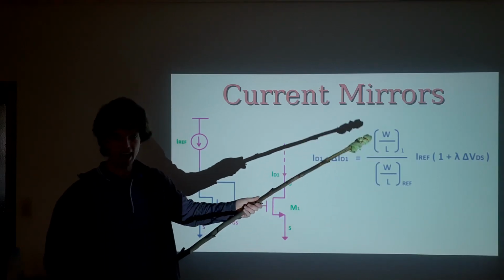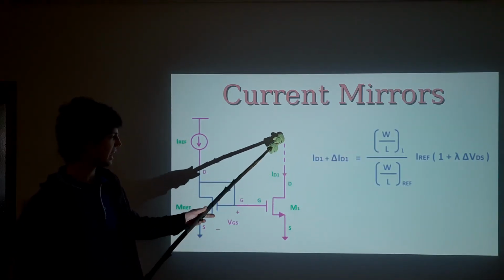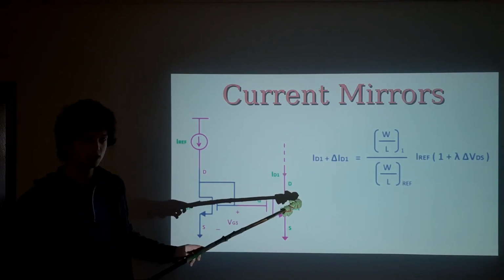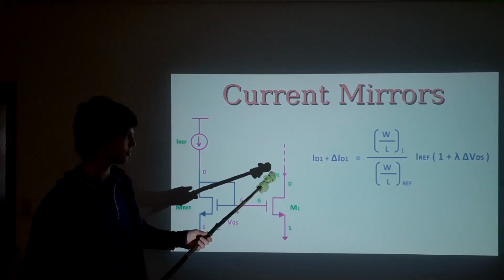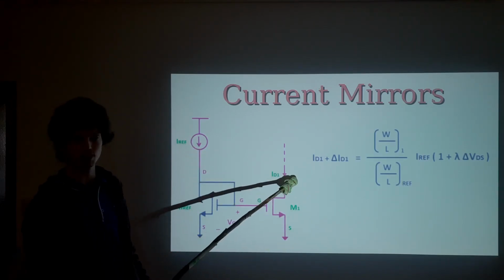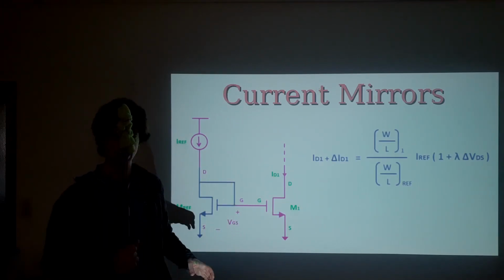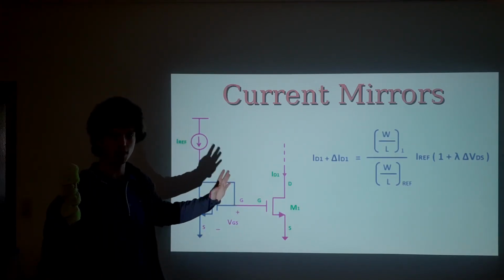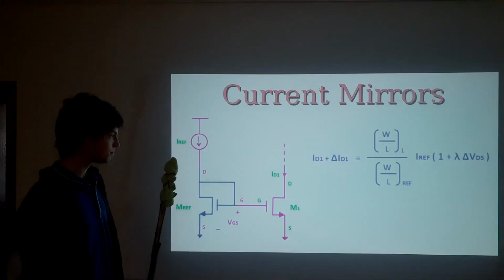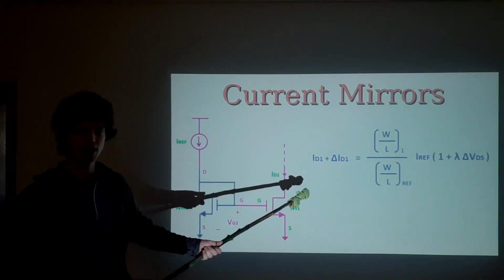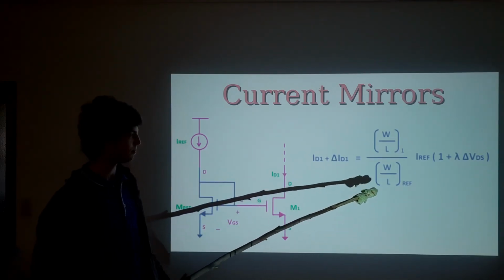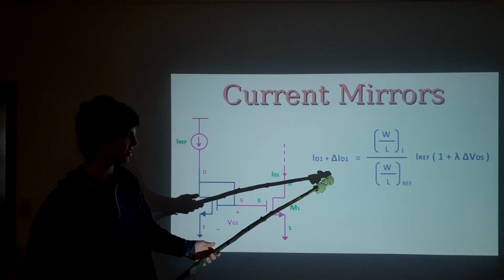And that is really handy because it means that we can have a really well-defined current over here just by taking these ratios. So we could rig this up in such a way that if we've got an amp over here, we can have 3/5 of an amp over here and know that that's what's going to happen. So this is a basic principle that underlies a lot of current sources, and it's really handy to know. And basically all you need to do to know it is know how to use that equation and plug it in, right? There's nothing that tricky in it.